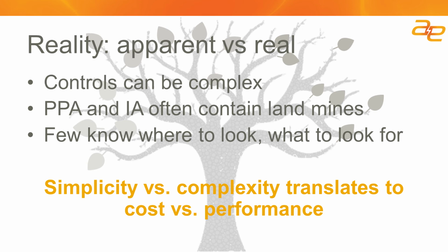The power purchase agreement and the interconnection agreement, most of the time, that's where the hidden surprises are found. So if I'm engaging with a customer on doing a control system, I definitely want to read through with particular care around the power purchase agreement and interconnection agreement for the things that tell me that there are requirements that aren't normal for most sites.